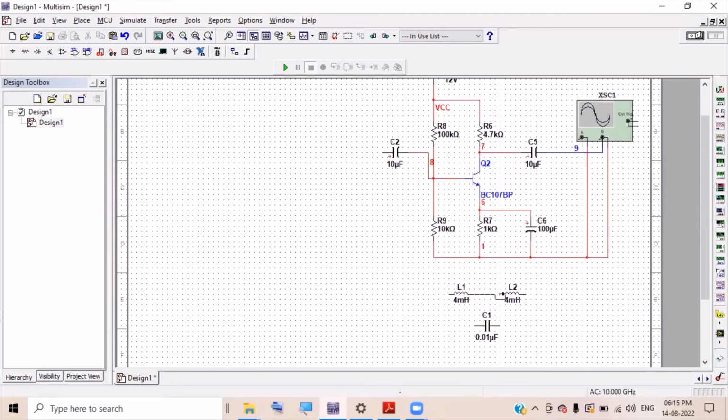Let me click this one here. So the two inductors you have to connect. Then this inductor end we have to connect to the capacitor. So I'm clicking here. Then one more click and joining this one here. You can adjust the capacitor. We'll drag that and adjust this one like this. This capacitor end has to be connected to the inductor.